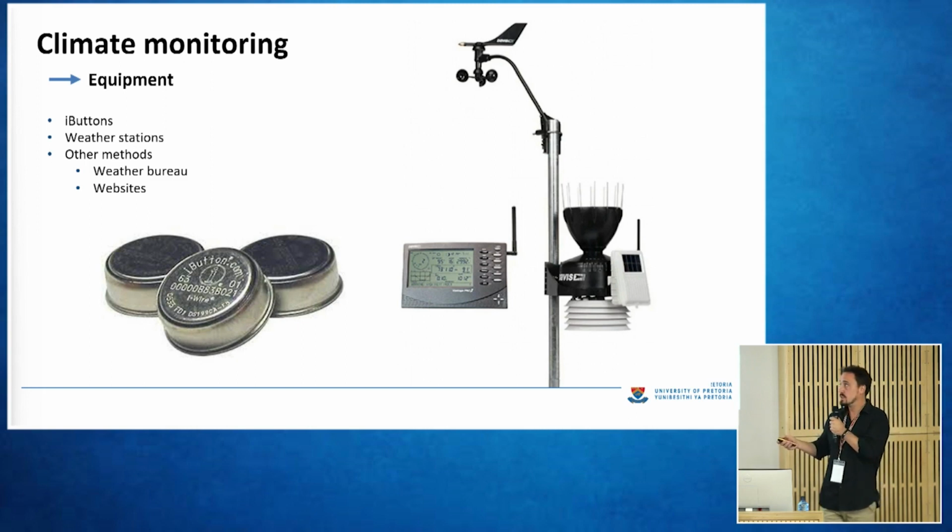So we put these inside caves. Important about these is that they're not actually waterproof. A lot of people do seal them in wax, but when you do this, you need to calibrate them again. So just pop them in a water bath and see, if the water bath is at 25 degrees Celsius, at what temperature do they then pick up?